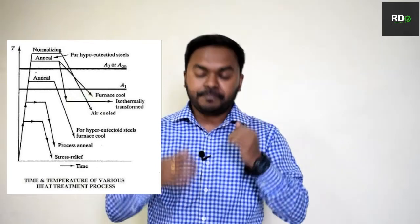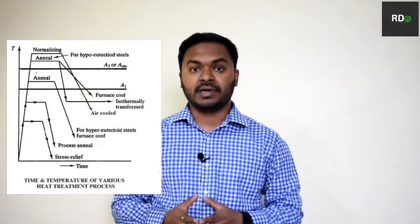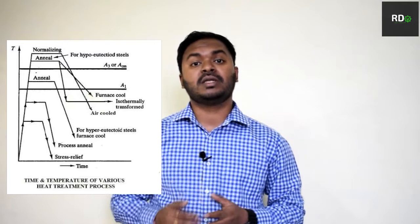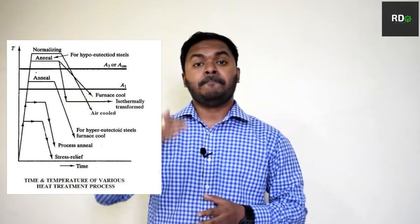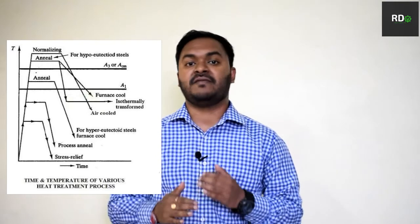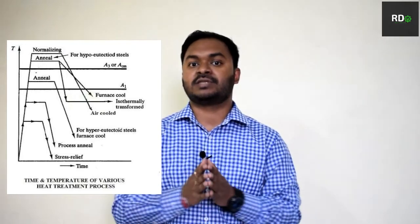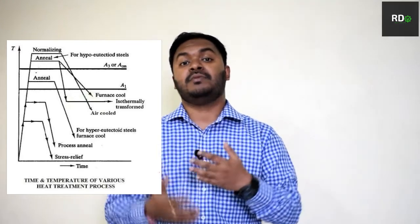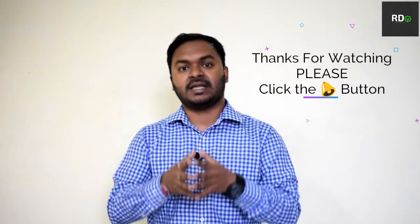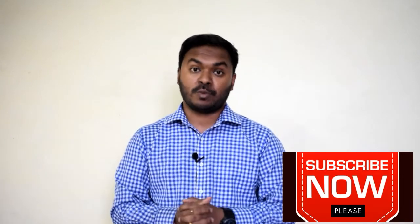In the full annealing, we treat the material 50 to 70 degrees Celsius more than the critical temperature, and in the process annealing, we keep the temperature lower than the critical temperature, and in the spheroidized annealing, we keep the temperature more than 750 or 770 degrees Celsius. It is all for steel. And in the case of stress relieving annealing, we keep the temperature more than 650 degrees Celsius. So this is all about the annealing heat treatment and the types of annealing.